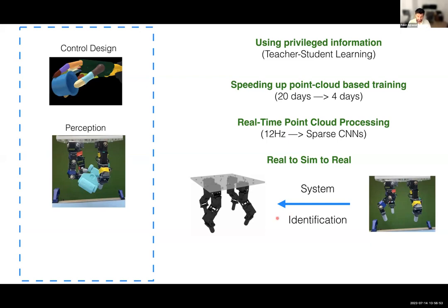And then there were considerations about the particular reward function that we were using, and also the hardware. And when I say hardware, it's the arrangement of fingers, but also the fact that we used soft fingertips that we iterated over. And what we found is using soft fingertips really helped in getting better generalization, even though the whole system was trained in a rigid body simulator.